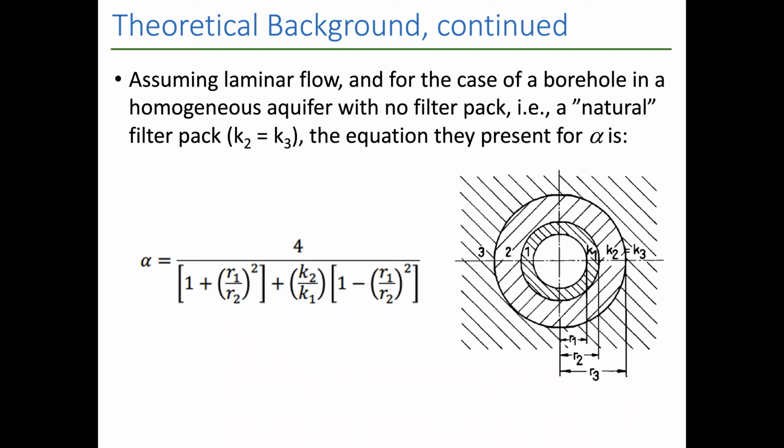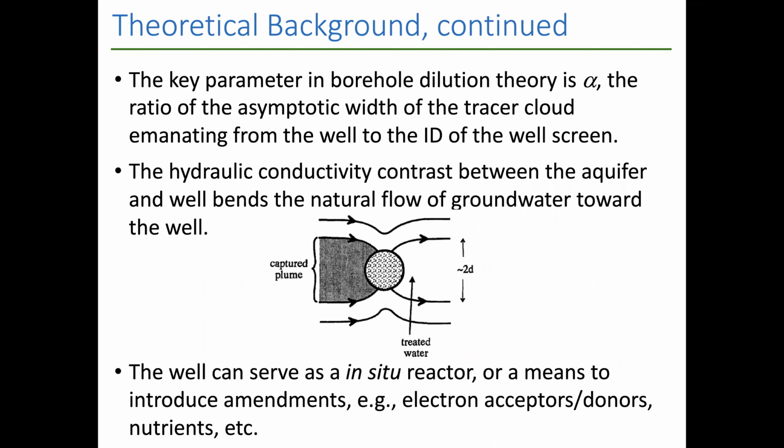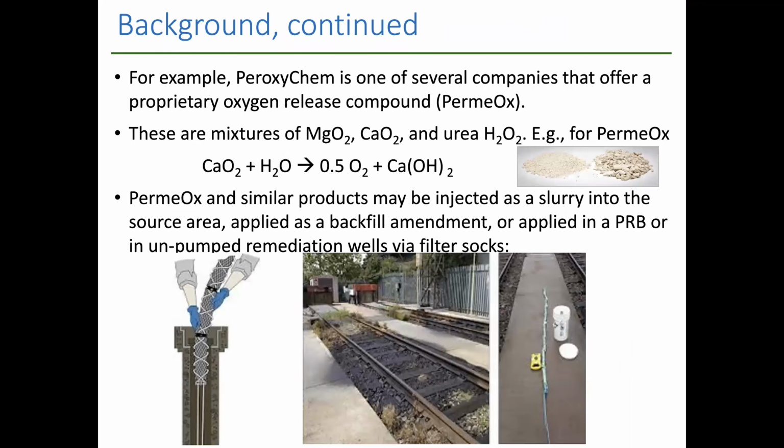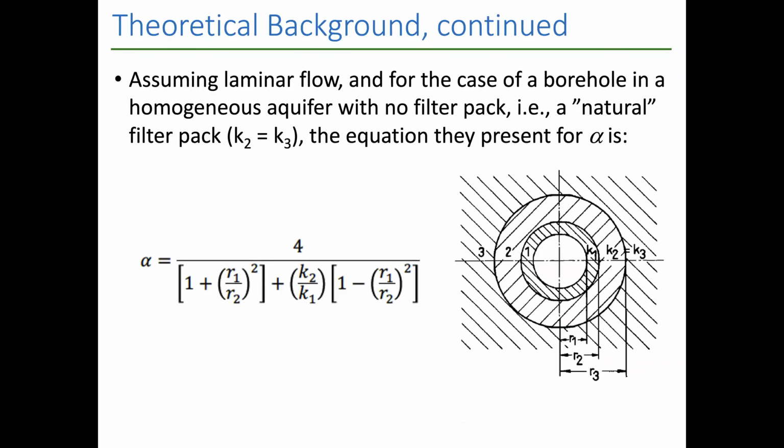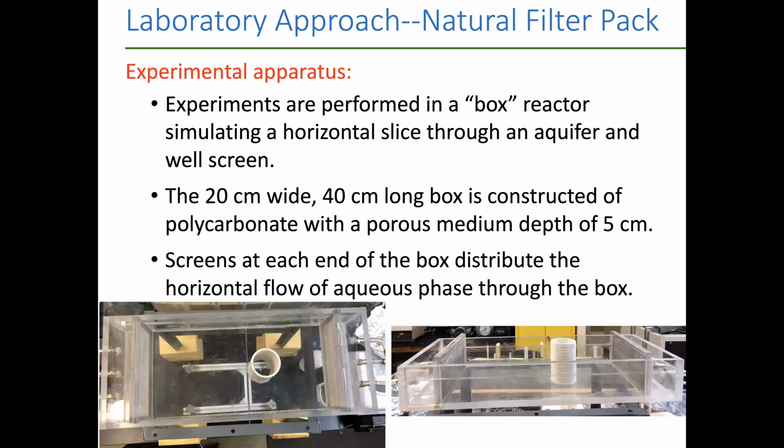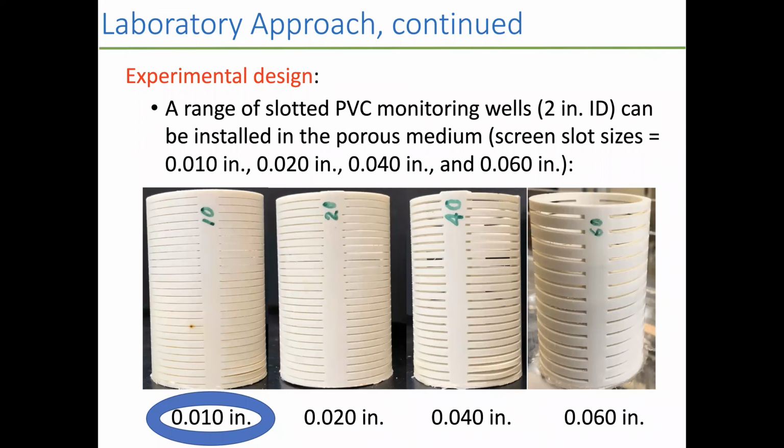Well, thanks. I found that really interesting too. You and I have had discussions about some of this, and this one issue is something I can't remember what the conclusion was, so I'm going to bring it up again. It has to do with the type of well screen. I think for the experiment with the filter pack, using the slotted screens that are cut into the PVC is not as conducive to spreading as if you'd used a wire wrap screen, even a plastic one.